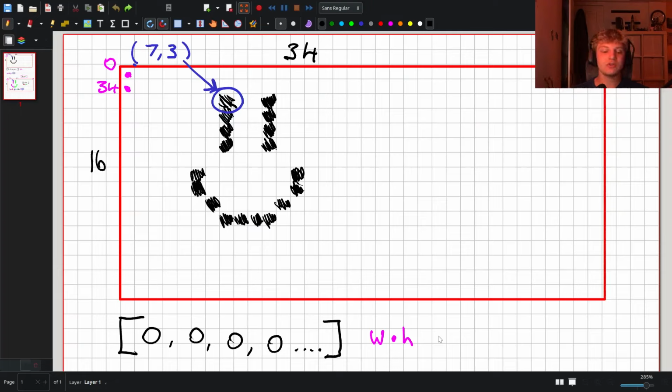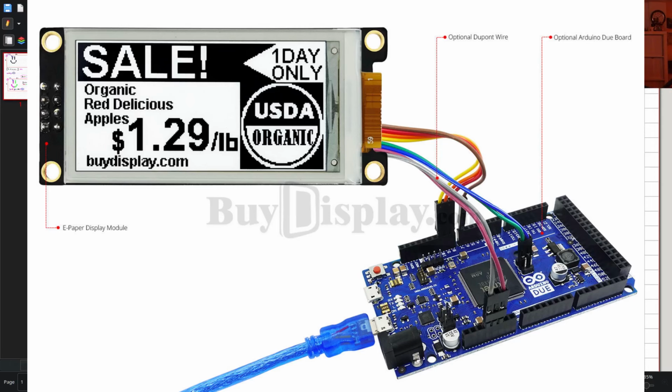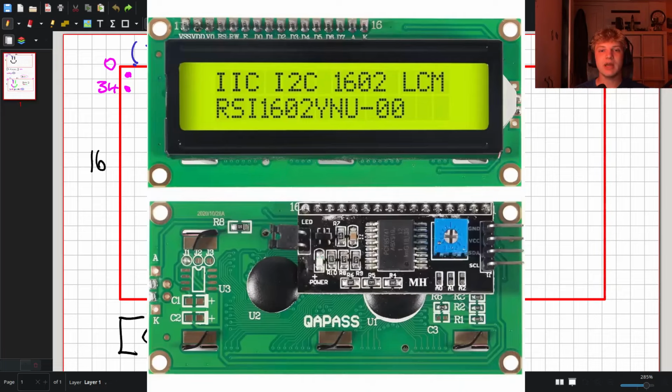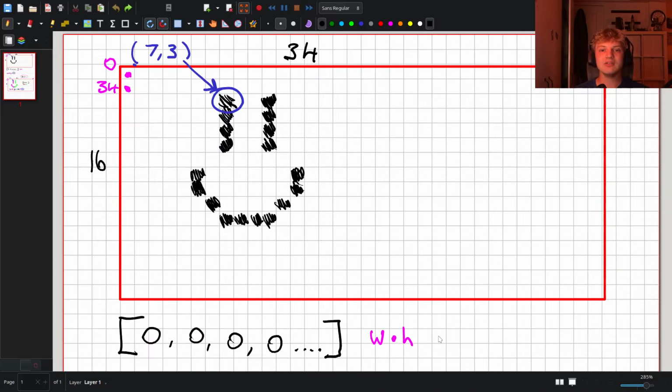And there's also this particular display that we're going to be writing the driver for. This uses a mono frame buffer. It's an e-ink display where a 1 might represent a white tile and a 0 might represent a black tile. So mono is not necessarily blue and white or black and white. Mono really just refers to you have 1 bit available, and those colors could be anything. I could have a red base and a green set, and that would still count as a mono frame buffer because I'm still using 1 bit of color to describe the image on the display.